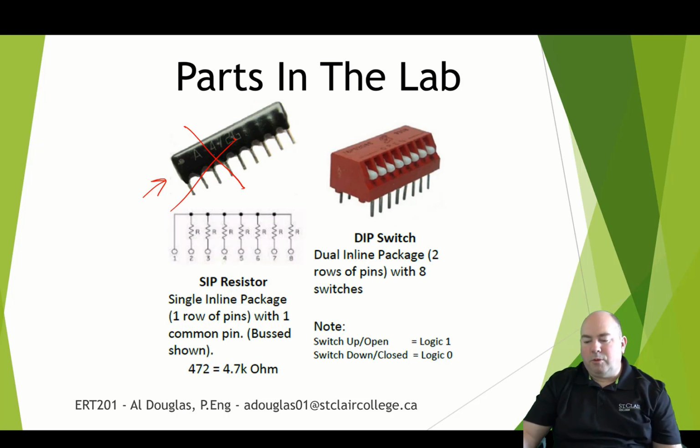The dip switch, dual inline package. There's a couple different sizes of them in Tinkercad that we will use, but this is basically a package with 8 switches in it. You can see dual inline package, meaning 2 sets of pins. So this pin here and this pin here. We basically can connect up on our board.